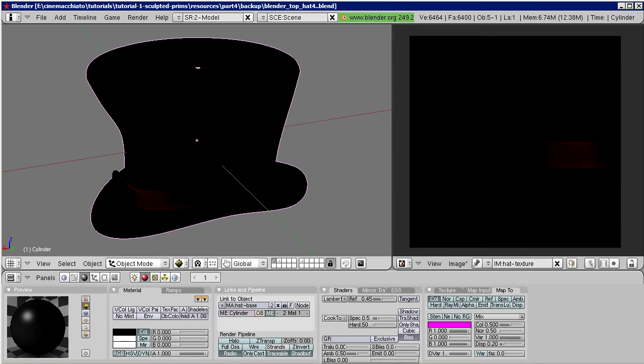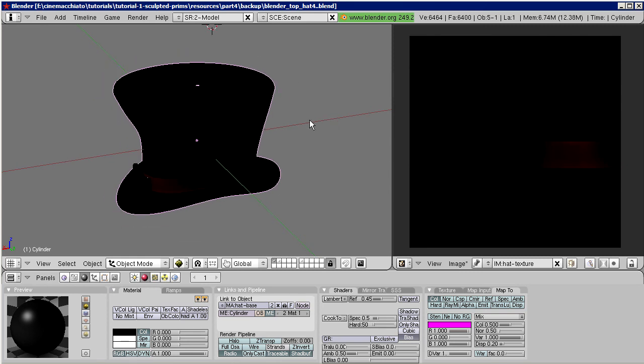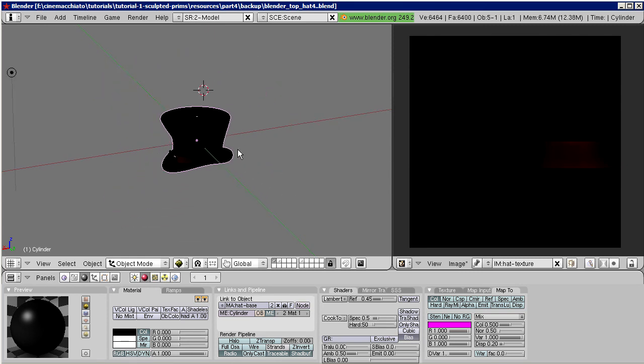Please note that normally we will set up light in such a way that all objects look nice from the camera location. You would not necessarily take care about parts of your object which point away from the camera. But for baking textures, this is no longer exactly true. You will want the object to be illuminated in a different way. Here is one possible way to go. We will use 4 lights in total.